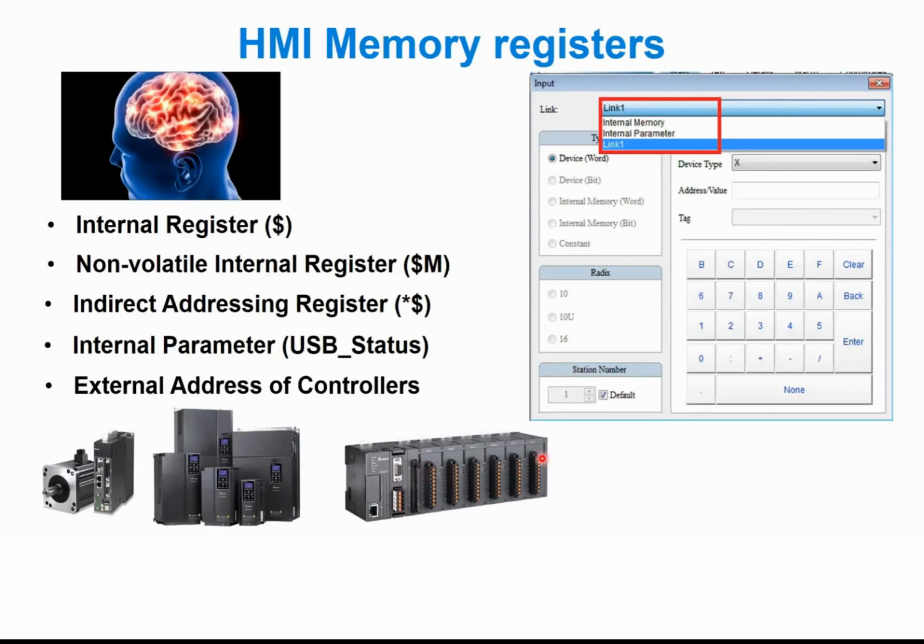So that's why industrial automation products are easy to program, because they have their own internal memory. Like also this is a VFD, variable frequency drive. So this one has its own address. There's an address for the speed if you want to set the speed. So just write the speed address from the HMI. Immediately you will see the drive start running at the speed that you have chosen.